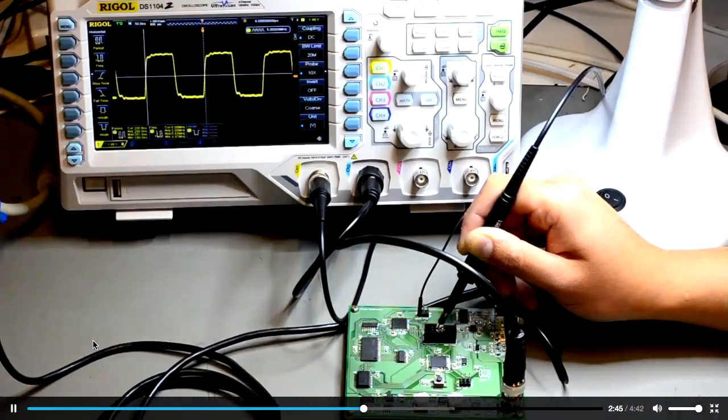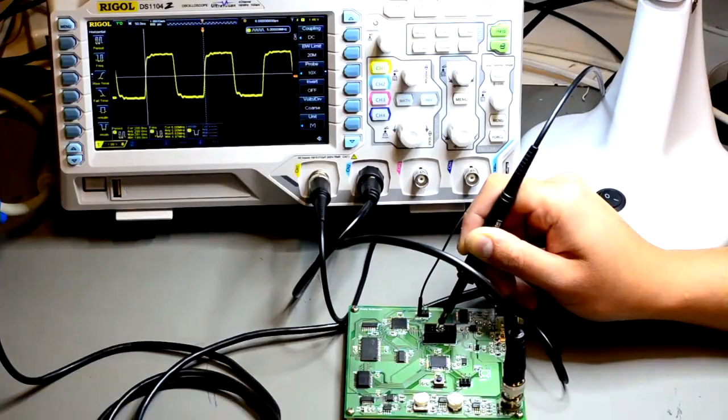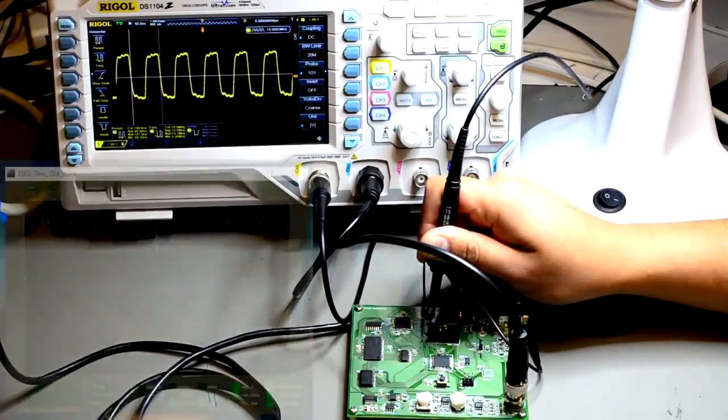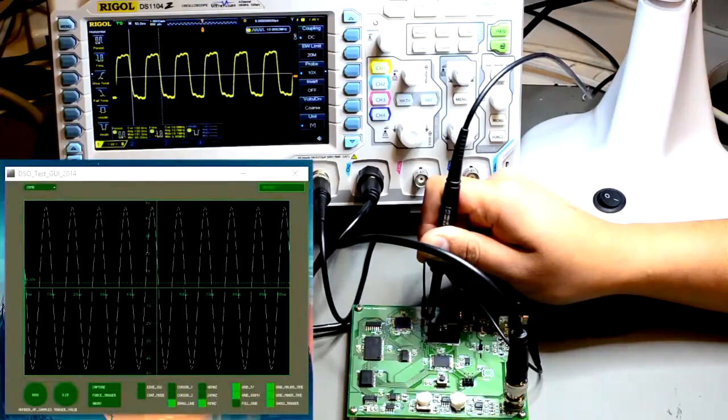The PLL. If the microcontroller has been properly programmed, you should see a 5 megahertz square wave coming out of the clock pin on the microcontroller. If you don't see 5 megahertz, then you need to check your fuse settings on the microprocessor. This 5 megahertz signal goes into the PLL, which multiplies it up to the clock for sampling in your oscilloscope. In the GUI, you can change the multiplication rate of the PLL, and you should see different clock speeds.